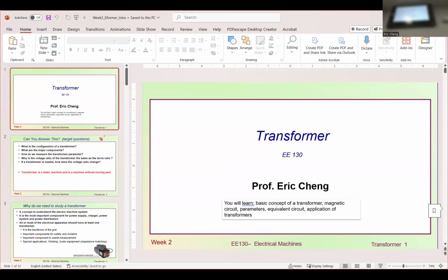So we're going to use the oscilloscope to apply some voltage to a transformer, and then measure the current. We have a current probe to measure the current, and then from the voltage and current we get a phase angle. Then you can use that to calculate the inductance and the resistance. So you will have more detail tomorrow.